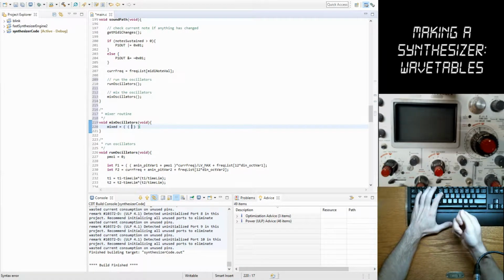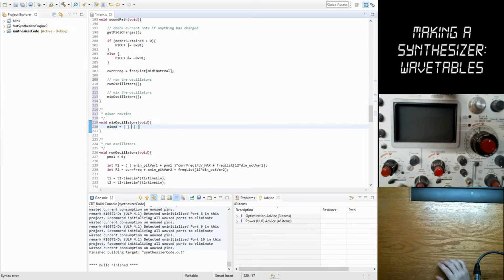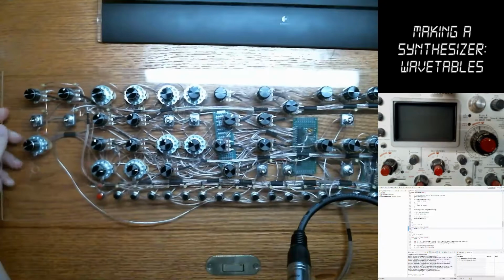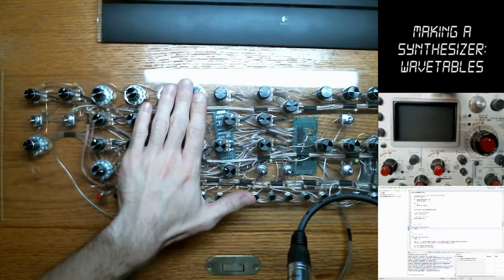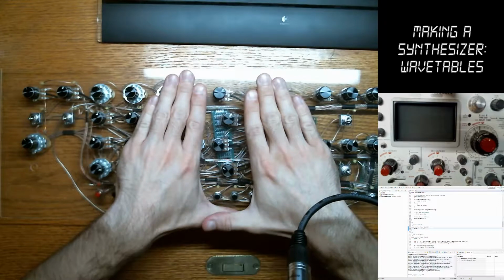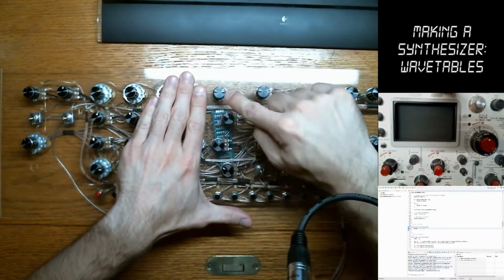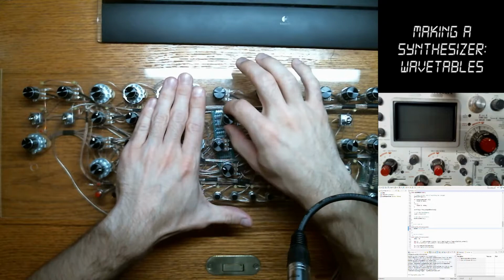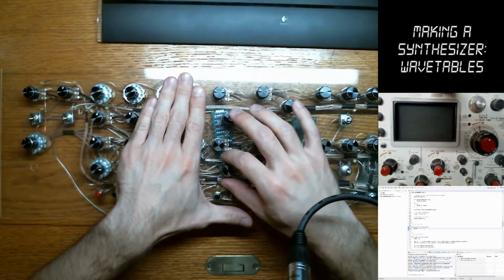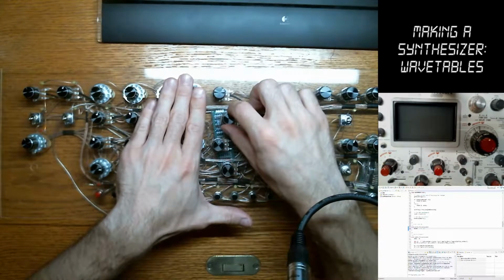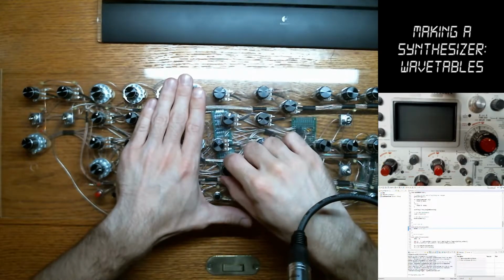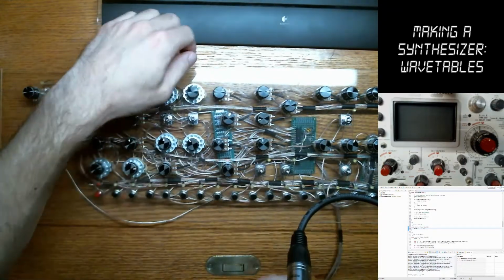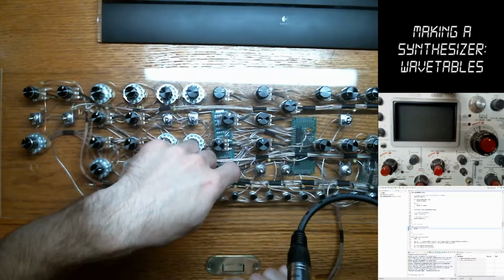This is also going to have some knobs in the mixer, which actually, let me show you that. Pull this back out. So our mixer here. So these are the oscillator 1, oscillator 2. The mixer is this location right here, or these knobs right here. There's 4 of them. One for level of oscillator 1, one for the level of oscillator 2. This one, or this one, I haven't decided yet, which I guess I will in a bit, but one of these is an external input, and the other one will be a noise. And it won't be a pink noise or anything, it'll just be plain white noise. So not only will we mix these in, we'll also have to generate the noise.